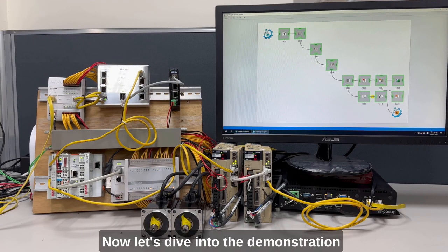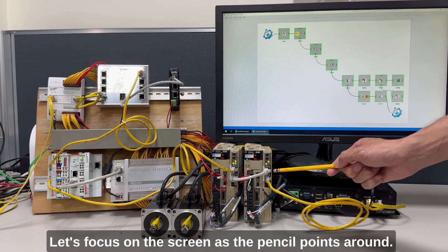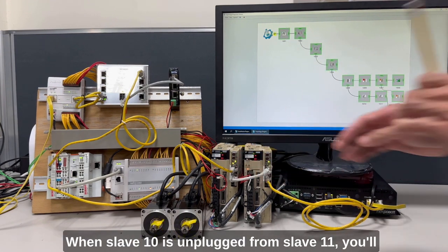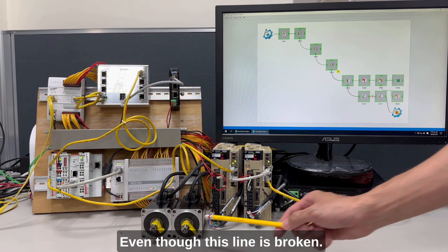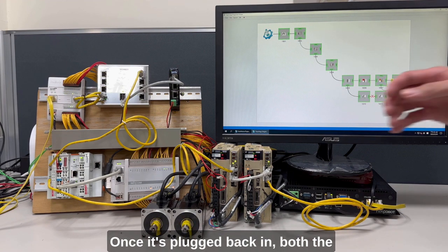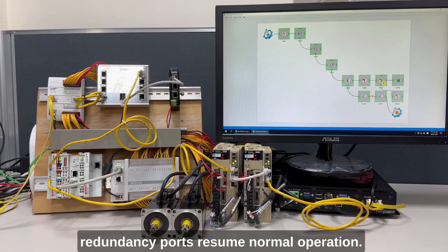Now let's dive into the demonstration and see how redundancy works. Let's focus on the screen as the pencil points around. When slave 10 is unplugged from slave 11, you'll notice that all the other slaves continue working, even though this line is broken. Once it's plugged back in, both the EtherCAT frames sent by the primary and redundancy ports resume normal operation.